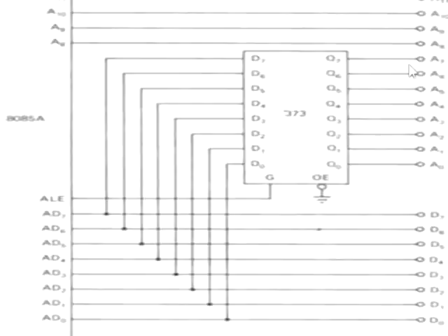Now this bus AD0 to AD7 is free. So now this bus is used to connect the data bus. The data bus from memory or the data bus from peripherals is connected straight away through AD0 to AD7. This is how the demultiplexing is done with the help of ALE.